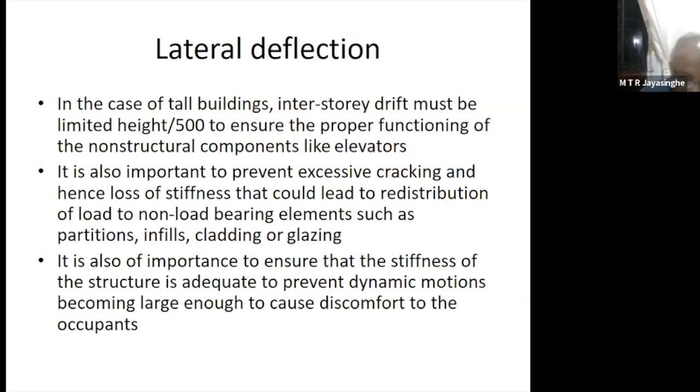So on one side, you have to use higher strength materials and optimize the structure. That is the vertical load carrying system coupled with horizontal load carrying, the horizontal members which are actually transferring the vertical loads onto the vertical load carrying system consisting of columns and beams. So steps also can be optimized. Then the moment you optimize these and use high strength concrete in columns and reasonably high strong beams, then you'll find the stiffness of the structure has increased.